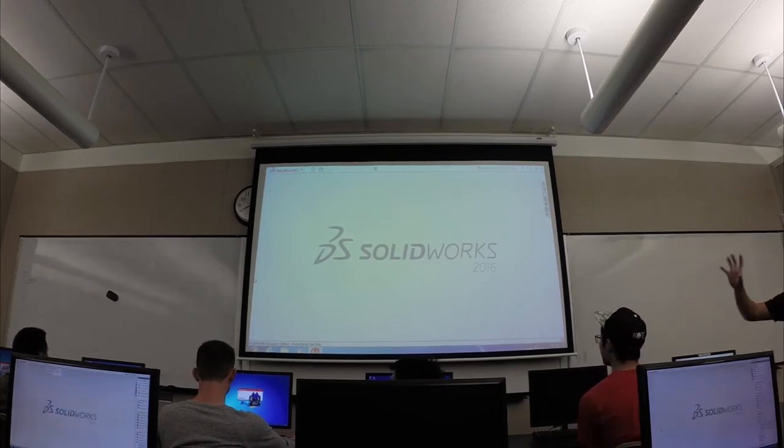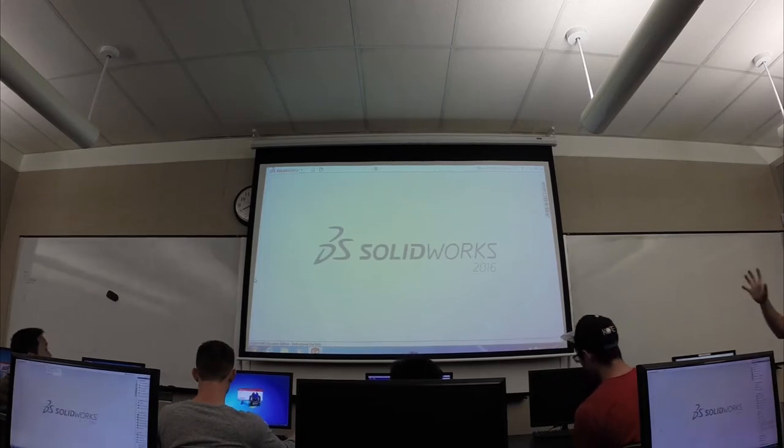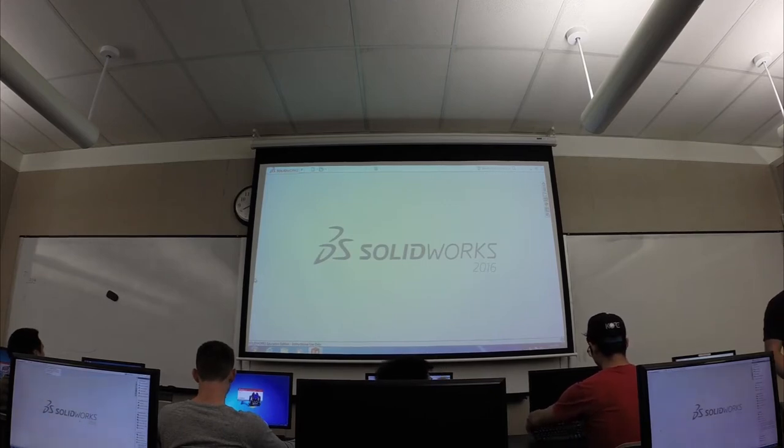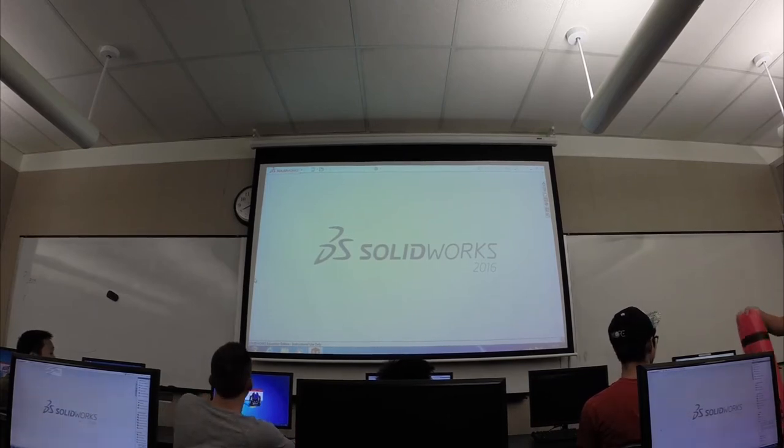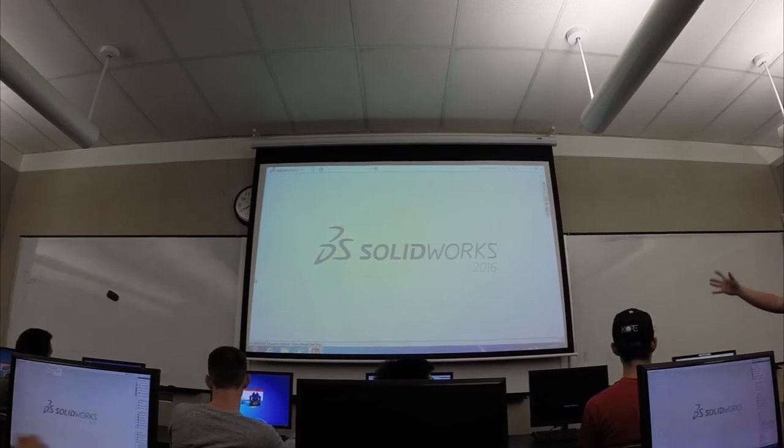So SolidWorks is a CAD program where what you do is called parametric modeling. The word parametric refers to parameters, right? What that means is that when you're designing, everything is based on references. If you imagine this large empty space, it's hard to pinpoint anything in that space without something to refer to, right? You don't really know where you are or what size something is. It all has to be relative to something. That's the premise behind this.